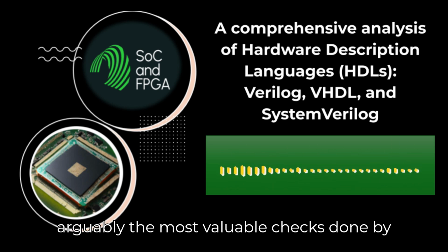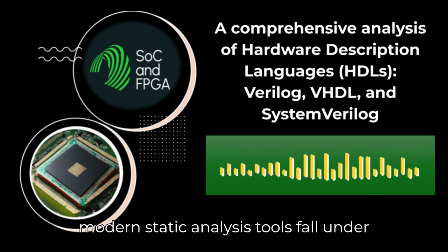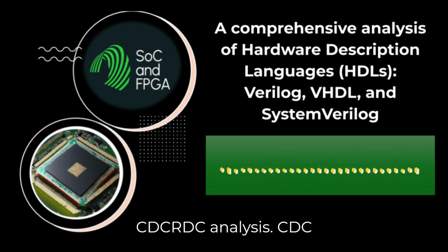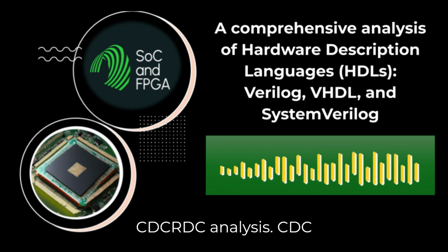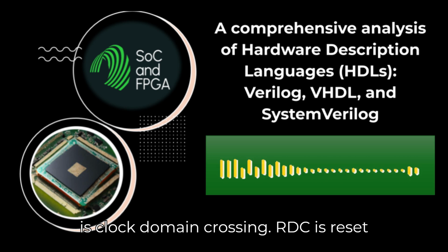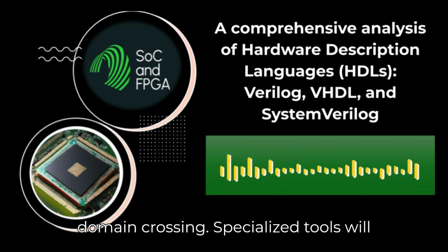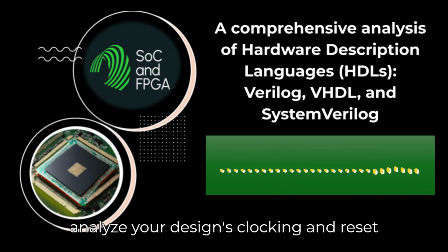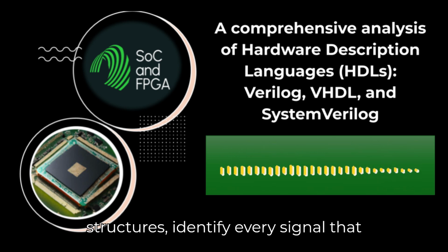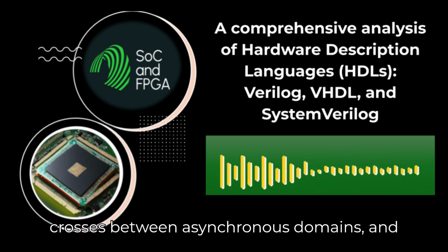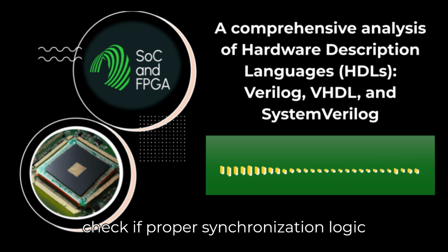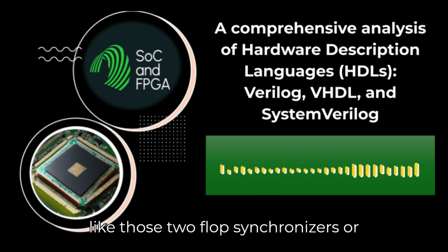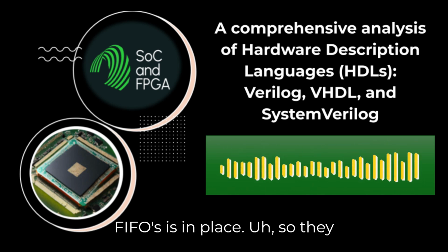Yes, but arguably the most valuable checks done by modern static analysis tools fall under CDC-RDC analysis. CDC is clock domain crossing, RDC is reset domain crossing. Specialized tools will analyze your design's clocking and reset structures, identify every signal that crosses between asynchronous domains, and check if proper synchronization logic, like those two-flop synchronizers or FIFOs, is in place.